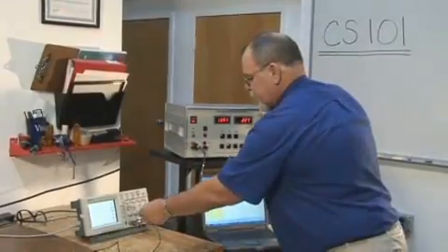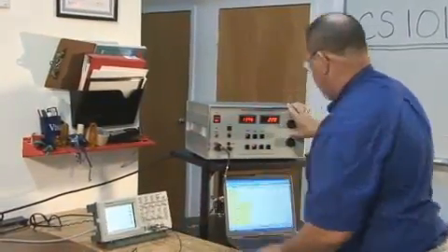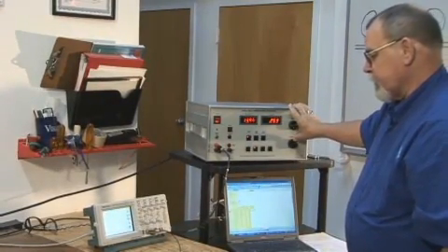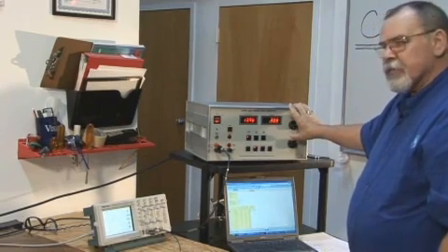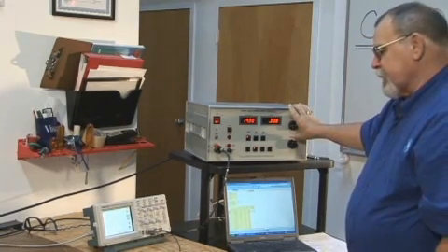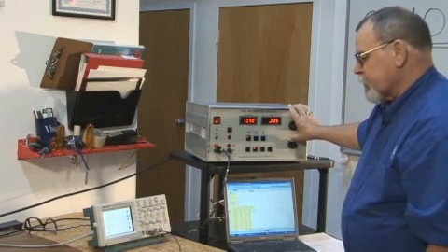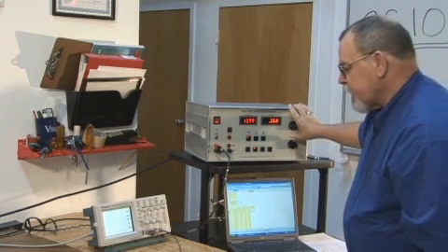I will constantly be adjusting the oscilloscope so I can monitor the signaling going on here. I'm maintaining the 6.32 volts. Notice that I'm not doing much with frequency. I'm not worried about what the frequency is at this point. I'm going to be constantly driving the frequency higher and higher and maintaining my voltage level.